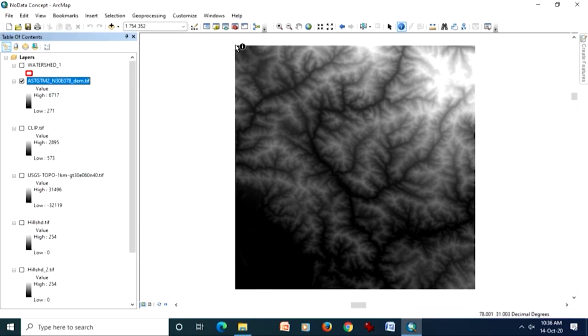If I put my cursor on the corner and read at the bottom, longitude it is 78 degree, and this is again, so this is a 1-degree tile. And same I can check for latitude, this is say 30 and this should be 31. Also, the name of the file which I have downloaded clearly tells us what is the extent of this tile.